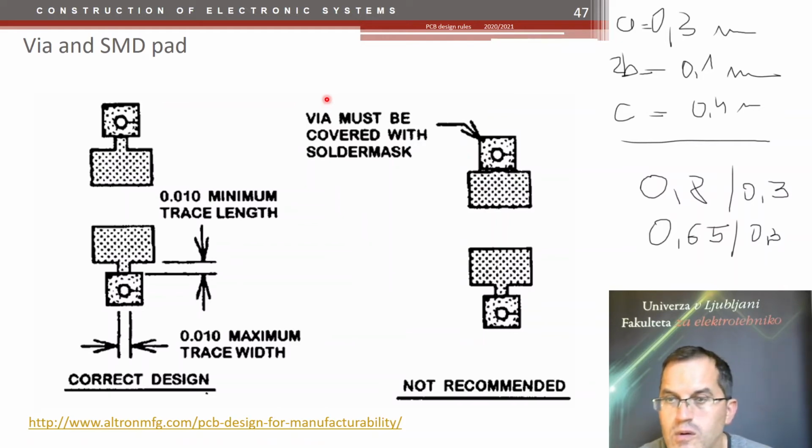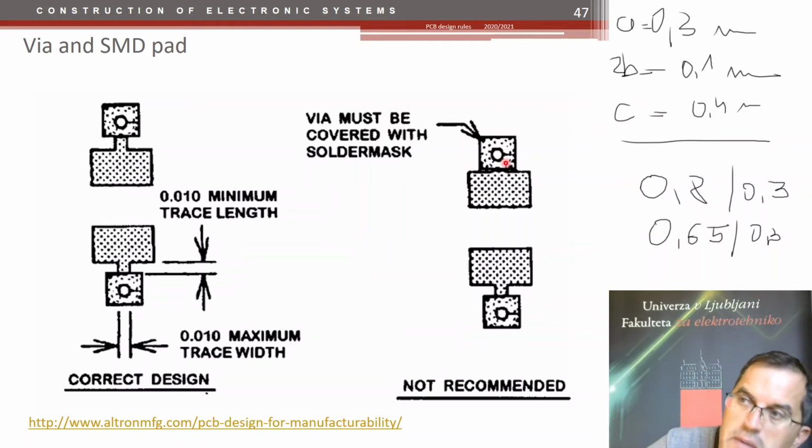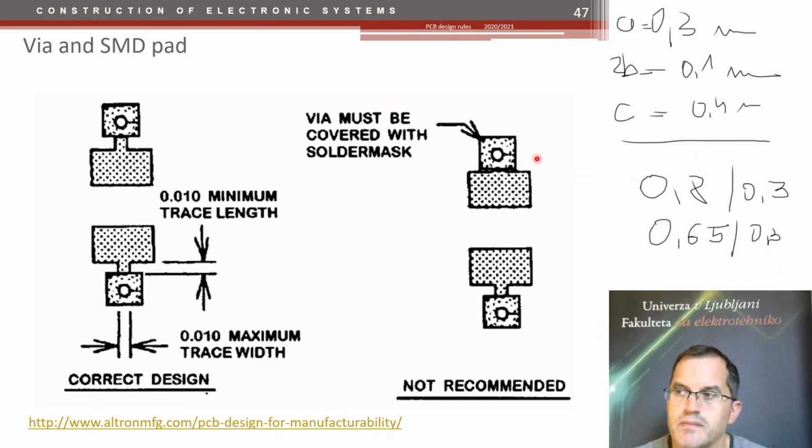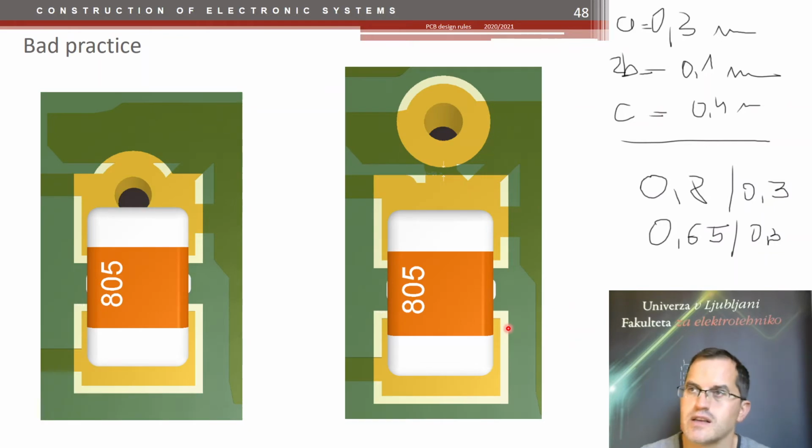If you want to put wire really close to the pad, which in case of, let's say, bypass capacitors, you will learn later, it's quite necessary, then it should be covered with solder mask. But then you should do it the same on both sides. So this is certainly not acceptable, putting wire on the pad or putting wire next to the pad but not keeping both sides of the same thermal conductivity, of same thermal properties.